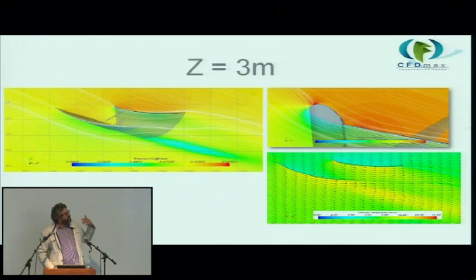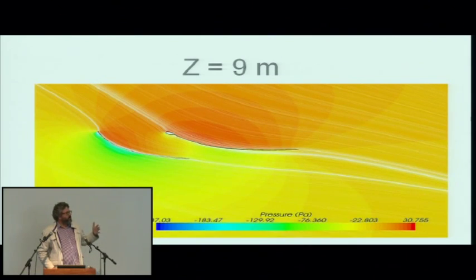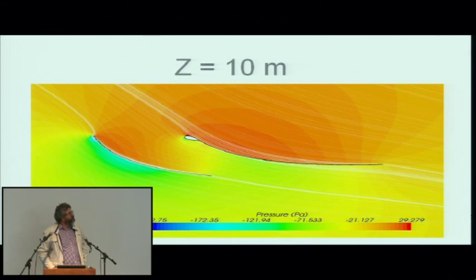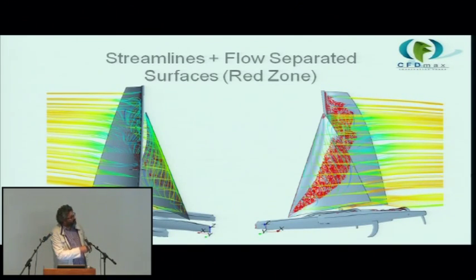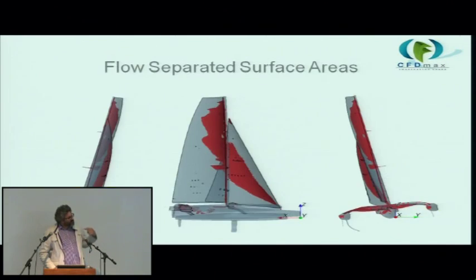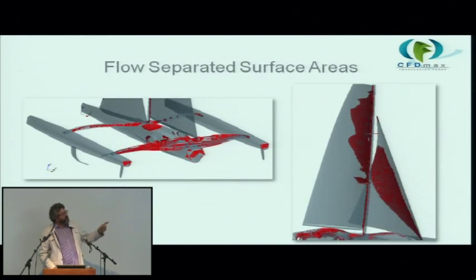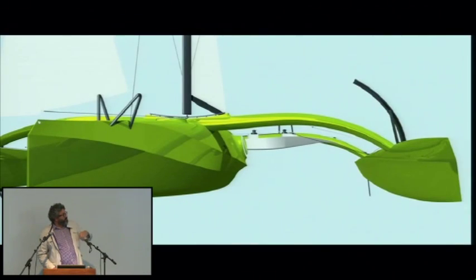So anyway, out of this analysis, which we probably spent definitely more than 6 months running, all this computational fluid dynamic analysis, what we would get is information like this, which is flow separation, which is a very bad thing, or unattached flow, and we would get stresses on the structure. So out of this, the naval architect, Fred Karubla, would then tell me, we need to change these surfaces and rerun them. And what was interesting is out of the dialogue between a naval architect with intuition about how things would behave, and me with no real idea about what I was doing, but ideas about surfacing and the computational fluid dynamics, we started to come up with things that hadn't been done, but which make a lot of sense.